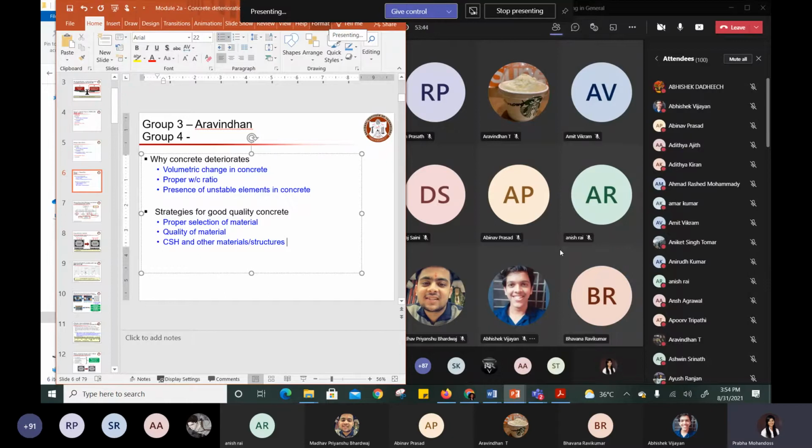If you are going for choosing a lightweight aggregate, then you can have many pores, but the pores should not be interconnected. When the pores are not connected, you will not have any problem with your concrete. But when the pores are connected, that will lead to a path for other elements to enter into your concrete. If it is interconnected, the agents entering your concrete will get stuck at that point itself. But if the pores are connected, then it can travel smoothly through the concrete and reach